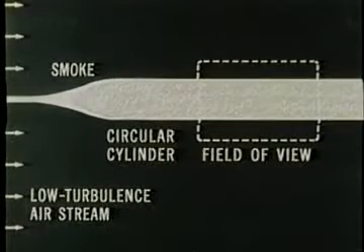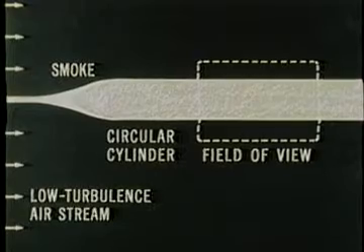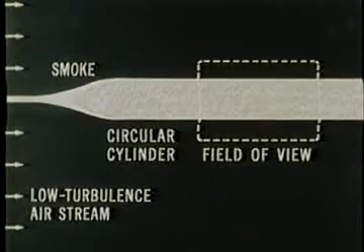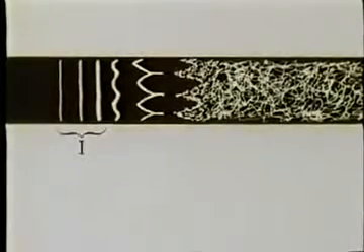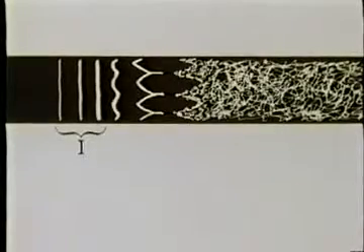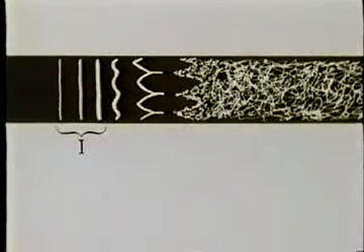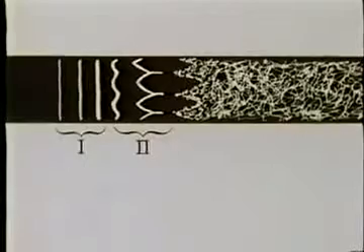The steps in the transition are very complicated and interdependent. Of nearly two-dimensional waves, the Tollmien-Schlichting waves, followed by the appearance and growth of three-dimensional disturbances associated with streamwise vorticity. Then turbulent spots can be seen. And finally, fully turbulent flow appears.